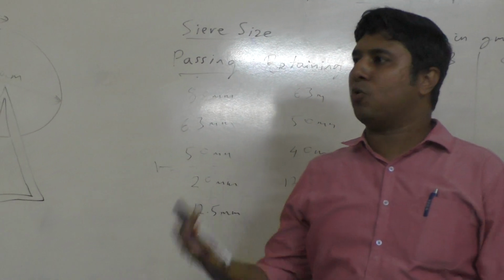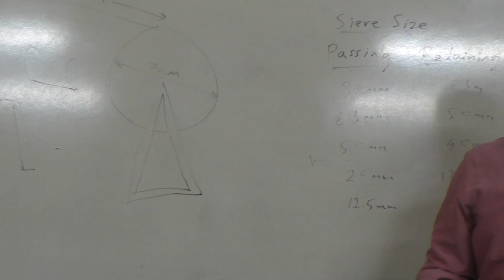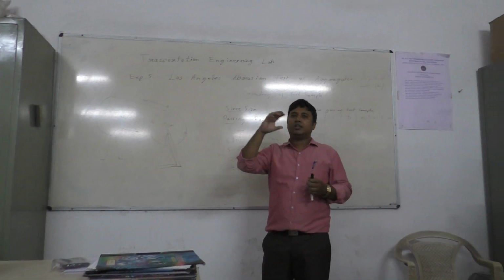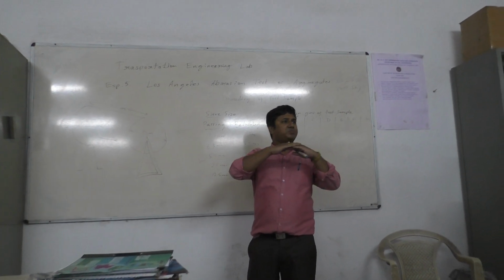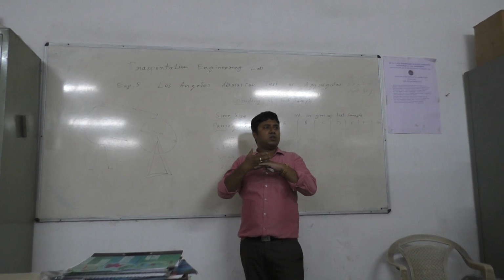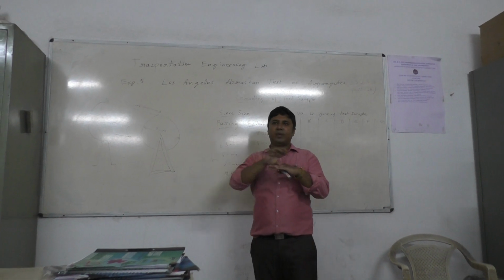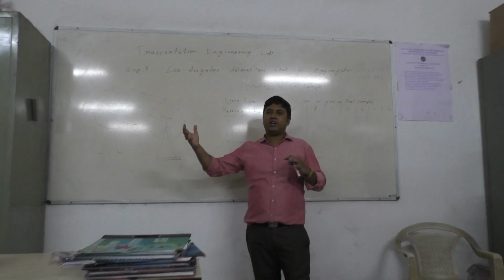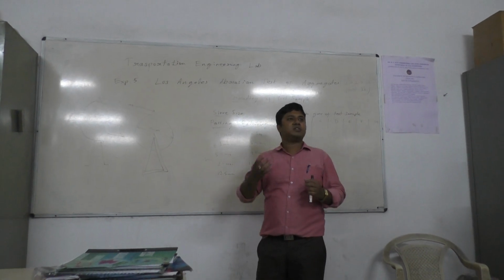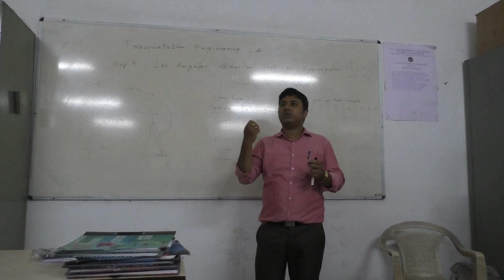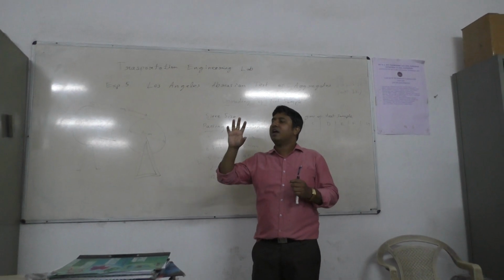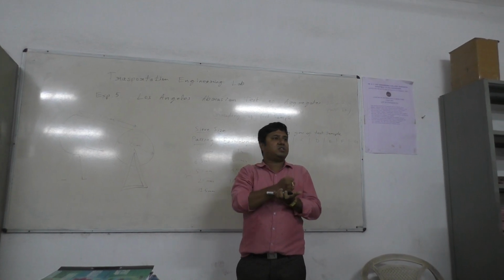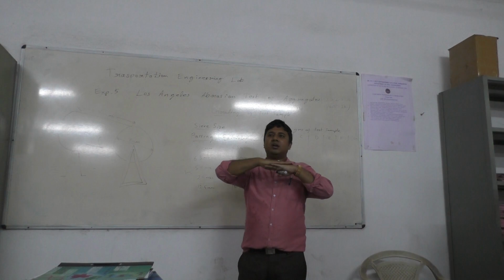Now, why is the abrasion test required in your transportation lab? In a practical scenario, when there is a pavement and vehicles are moving over it, the surface of the pavement is prone to abrasion because of the load of the wheel coming on the surface. There may be abrasive force due to heavy vehicles, or vehicles mounted with pneumatic rollers, like tanks or some goods carriers whose wheels have metal, which will have an impact on the surface in terms of abrasion. Means there will be some rubbing action.